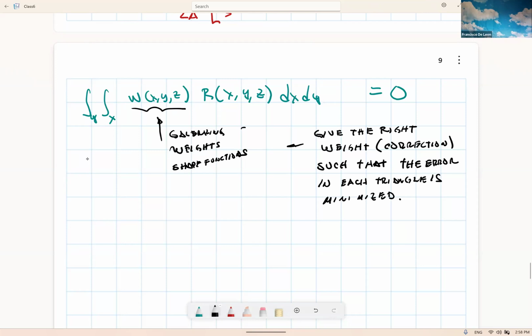The console gives you a quality measure of the meshing. When you do the meshing, it gives you a number related to how good the meshing is. Mostly it is related to how small the area of the triangles is. So when we had a complex deformation, there were very small meshes. When we increased the tolerance or correction factor, then the simulation converged. So it depends on the method.